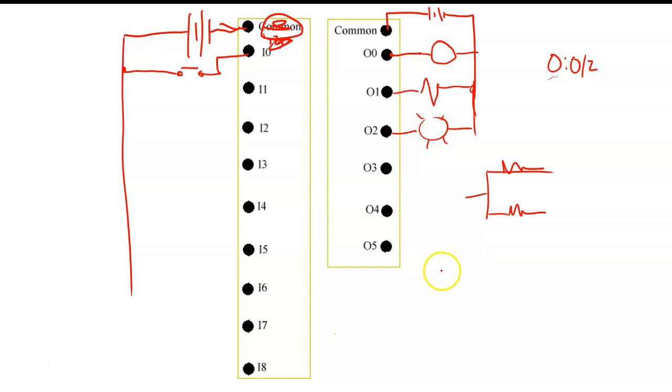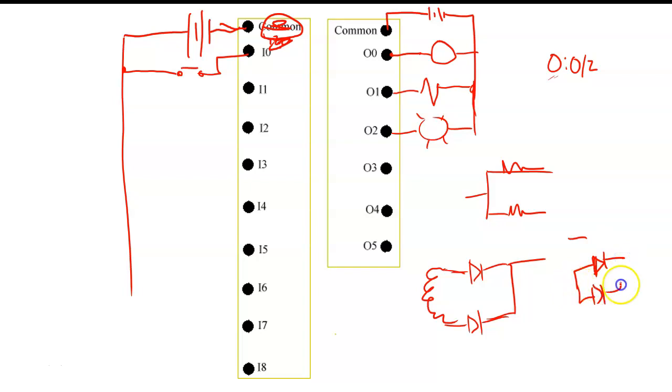We hook up this circuit right here. It's a rectifier circuit to turn AC into DC, and we'll come over here and connect these together. And then this goes to one side of the transformer, that goes to the other, and I'll go over there and look, and they'll have the diodes. Somebody in the class will have the diodes connected like this. They'll have them in parallel. But if it were in parallel, what? This side would be connected to that side, so we only got one side. So somebody's going to do that in the class.